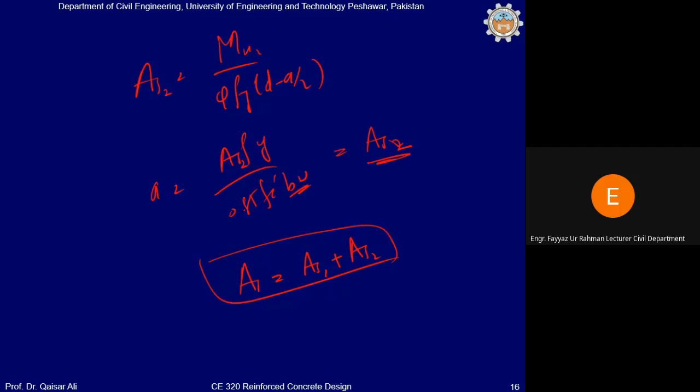अब यहां पर आप in the first trial a is equal to 0.2 d assume कर सकते हैं, but since you know that a is greater than hf तो आप डायरेक्टली a assume करें। यानी फॉर एग्जांपल आपके पास hf is equal to 4 inches, तो a in the first trial आप assume कर सकते हैं 4 inches। clear? Definitely it will be greater than 4 inches।